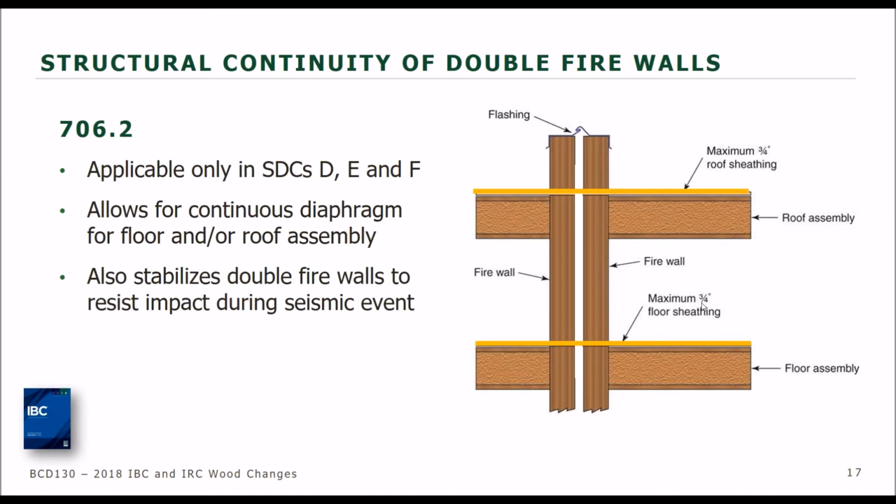And this is Jim. I think you're making the point that is exactly what was intended. The reason that they capped it at the 3/4 inch was to take into consideration that, if you had a 3-inch type of sheathing going through there for diaphragm provisions, the potential for that type of a failure during fire to have 3 inches of solid material going through the firewall might actually start impairing the building on the other side.